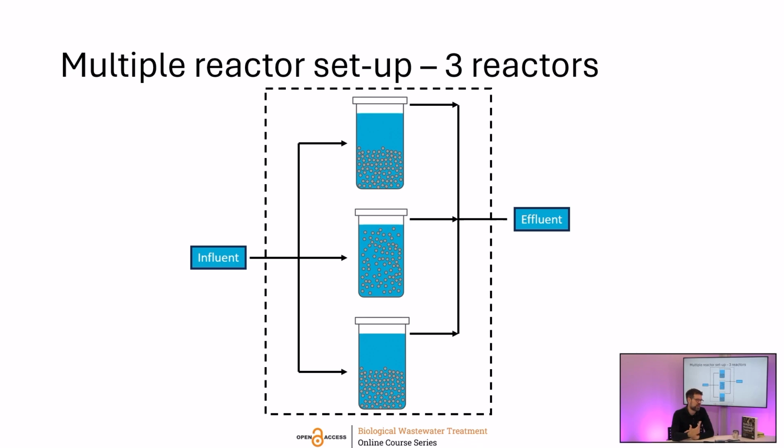So most of the time you will have multiple reactors set up, 2 or 3 or more, to constantly take in influent, and then one reactor is feeding while the other reactors are doing reaction or settling. When one reactor is done feeding, the other one can start feeding, and so on, so that you still have a continuous process, even though you have a batch system.